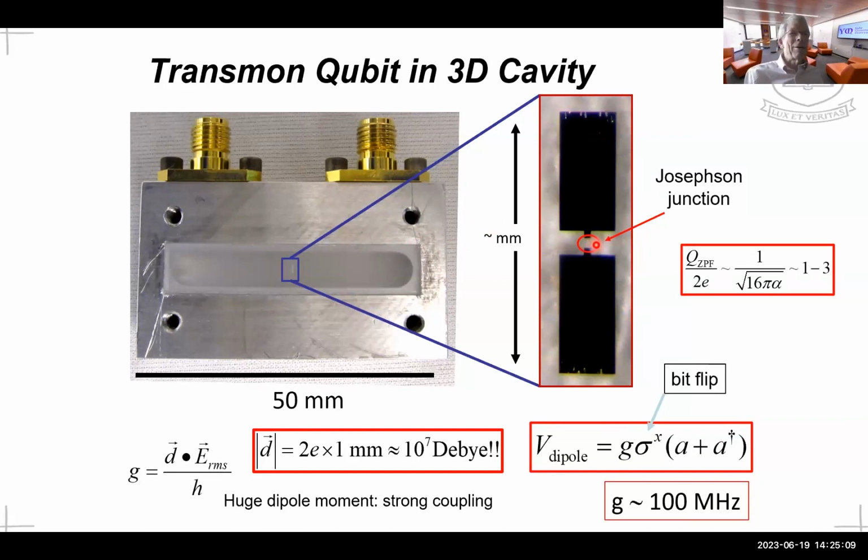It doesn't have much area, but the capacitor plates are only a couple nanometers apart. So it actually contributes about, what, Michael, 10% of the total? I think even less, yeah. Usually we just leave it off because it matters so little. So in other words, when you take charge from here to here, electric field lines go back from here to here. That's the geometric capacitor.